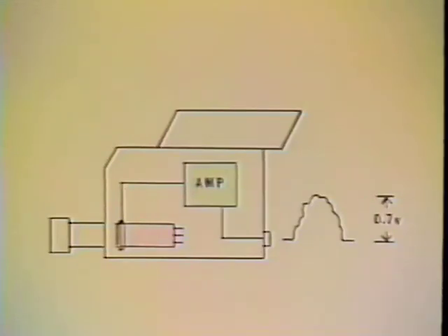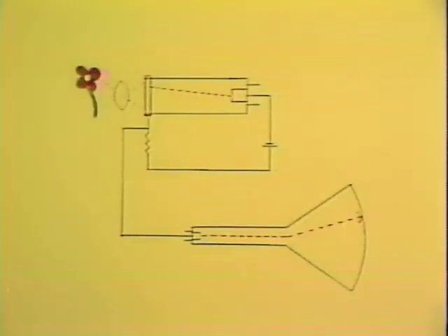At this point, we can now review the process by which a television picture is made. The scene to be transmitted is focused onto the target of the camera tube. The target is scanned by an electron beam. The beam has a very narrow cross-section, so it effectively splits the image of the scene into very small parts. As the beam scans across the target in horizontal lines, it effectively reads the image. The brightness of each section of the image determines the level of the output voltage.